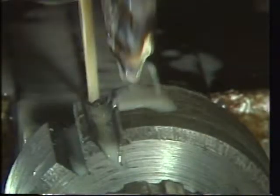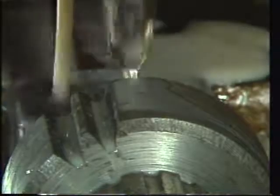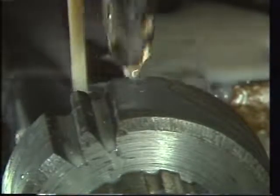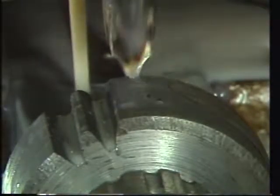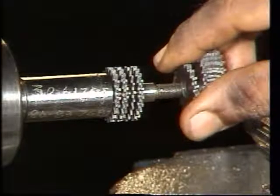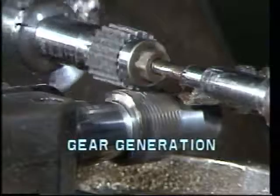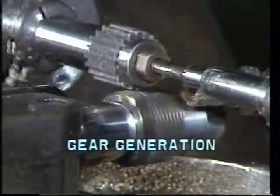Cutting of spur gear on a standard milling machine is carried out where production of a fewer number of gears are required. After cutting all the teeth, the depth is set for finish cut, and the same process is repeated. When mass production of spur gears with high accuracy and high speed applications are required, gear generation is employed.